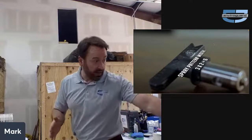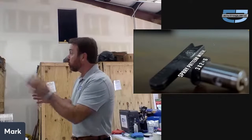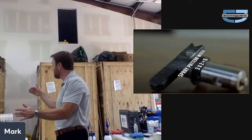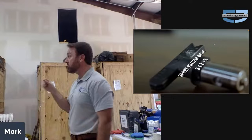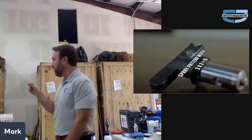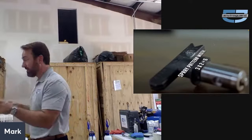So instead of an 11 on the backside there, it'll be like 21 hundredths of an inch, probably up to maybe 33 hundredths of an inch, which is a much larger orifice size.